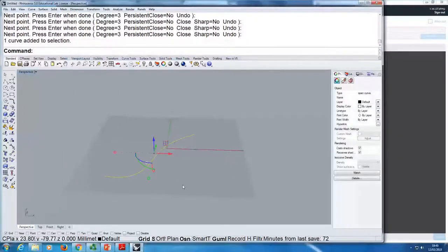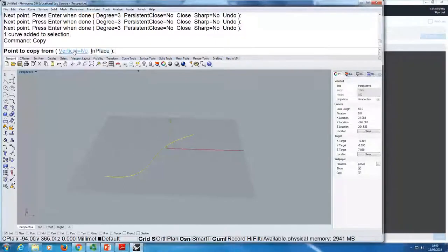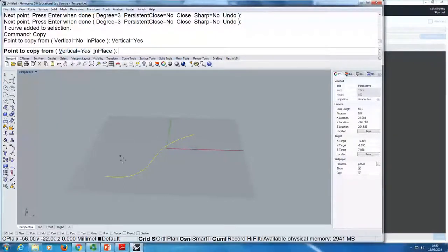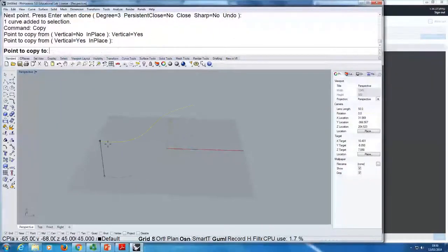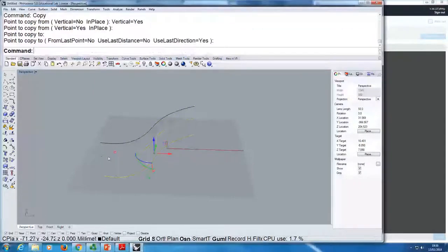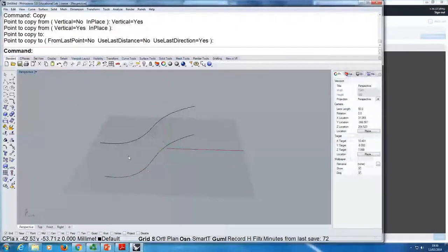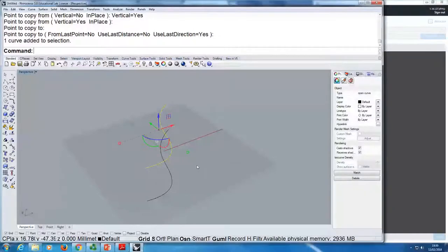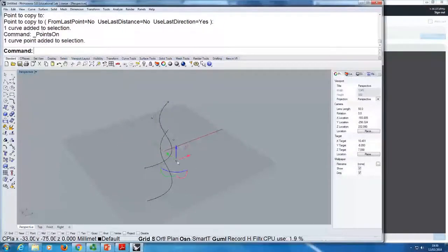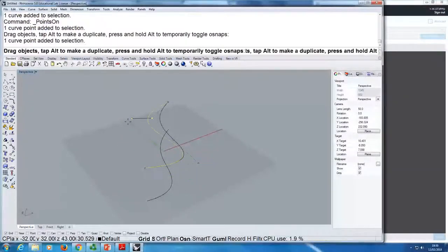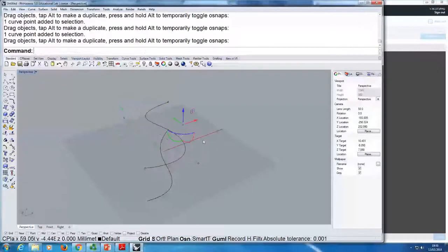And we copy it, copy vertical, just to make sure we're in the vertical from the endpoint. I want to create a surface, so I don't know if you remember how to create a surface between two curves: it is loft. Before I do that, let's just move a bit those control points. So again, if we press F10, just to create some funky surface, doesn't really matter.